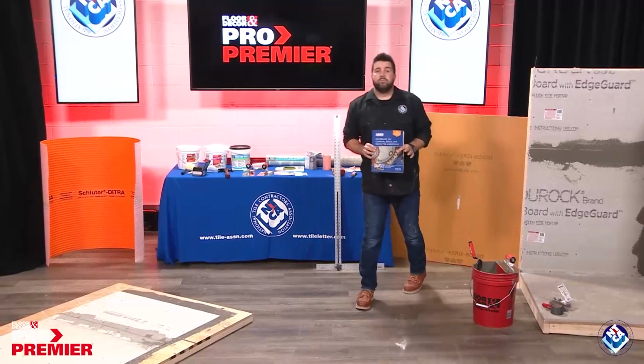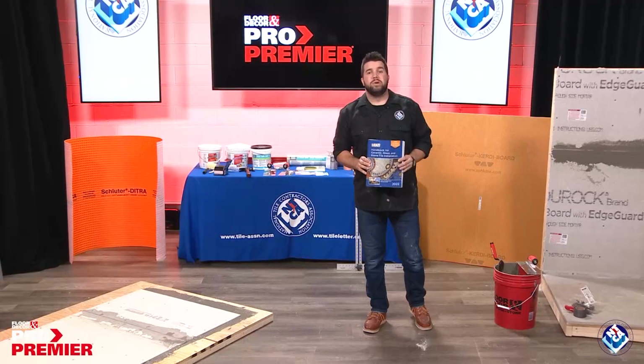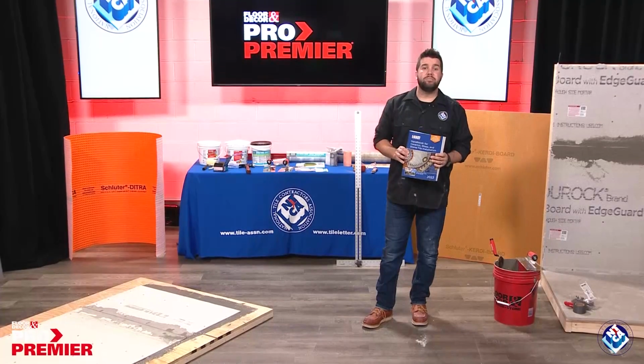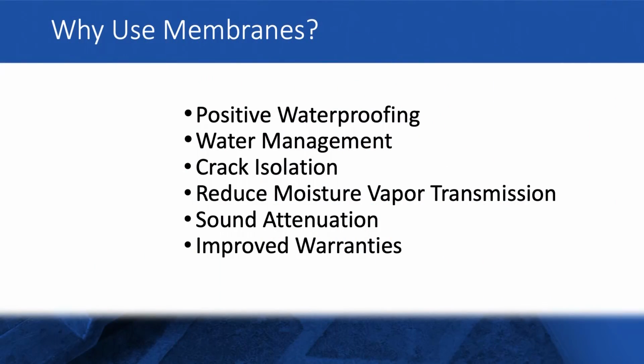The TCA handbook has 171 details. 35 details do not include membranes, 48 require membranes, and 88 details list membranes as an option. So why would we want to add a membrane? Well, we have positive waterproofing, water management, crack isolation, reduced moisture vapor transmission, sound attenuation, which means the reduction in the strength of a signal, and improved warranties from the manufacturer.